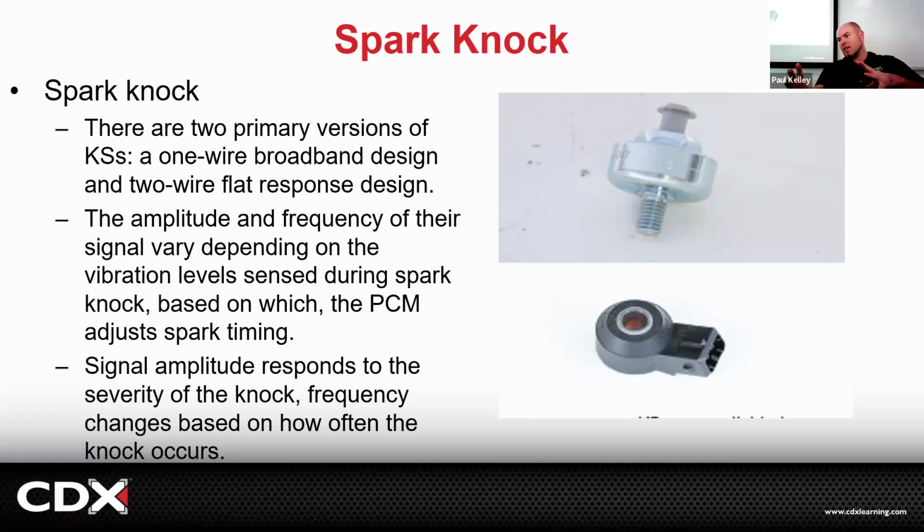All right. So let me explain octane, because we're going to go into fuels too. Octane is the resistance to burning. So if your piston's coming up and you've got high compression, supercharging, turbocharging, high cylinder pressure, it's going to tend to break those bonds in the fuel and start a flame, right? The reason we use 91 is because it's going to hold on a little longer till we can start the spark. But if you accidentally shoot 87, it's going to start the flame before the spark occurred. There's only 87 octane rather than 91.